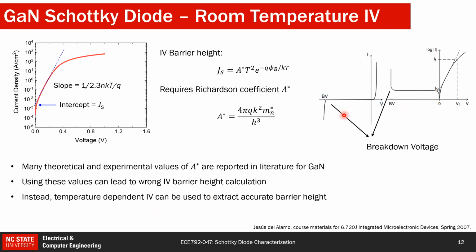Another thing, if I want to find the breakdown voltage, which I didn't do in my devices, so I had a schematic where I took it from the internet. It's very easy to find the breakdown voltage, because a sudden rise in the leakage current will tell you where your breakdown voltage is.